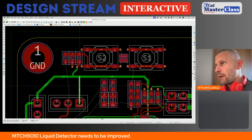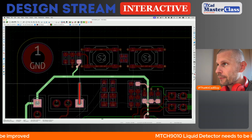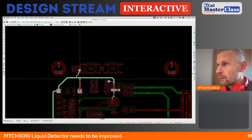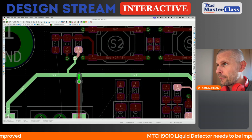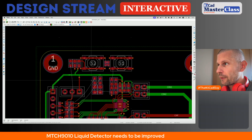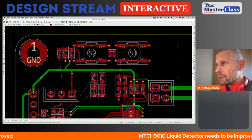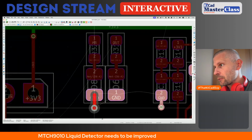Now what? I will need to route the bottom layer. Yes, the bottom layer tracks. So I will route it like this on the top layer, and it means there is the full width of this area that can be dedicated to these two signals.